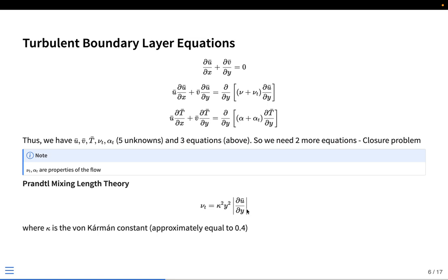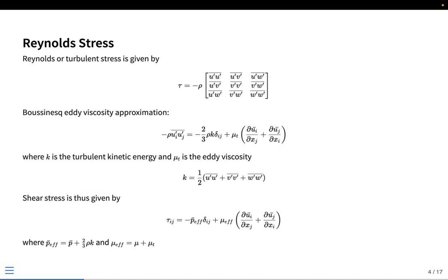So the one that I showed you here is, for example, we have the turbulent kinetic energy here. So there could be another governing equation, an energy conservation equation for this turbulent kinetic energy versus the dissipation terms, and that could also be used to simplify this even further. And there are several other numerical techniques to solve this, which we are not going into.